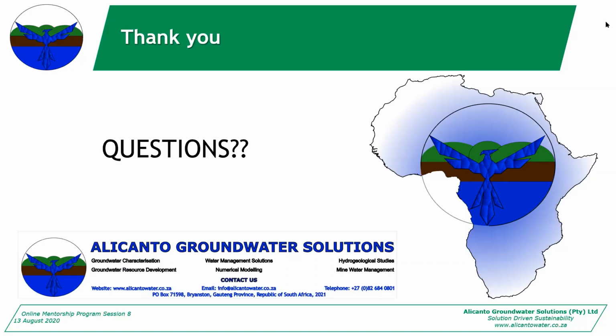Conductivity as well, or transmissivity, because we have point sources of data. We have boreholes that we've pump tested, so we need to interpolate between them. So there's a bit of a confidence issue there. And then storage. Storage is a big one because we don't usually do the proper pump test to get an accurate storage value. So those are the big three that I would recommend you start with for calibration, just to get an idea of where you need to look. Thank you very much. Noted, sir. Yeah, great. Armand, you had your hand up there?